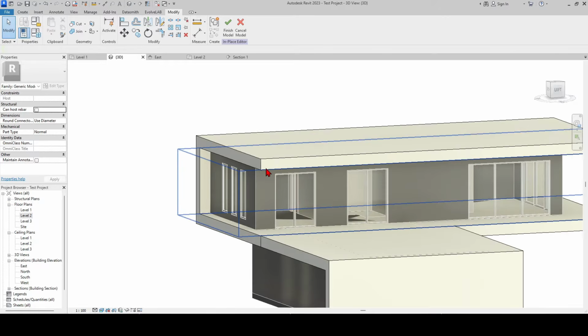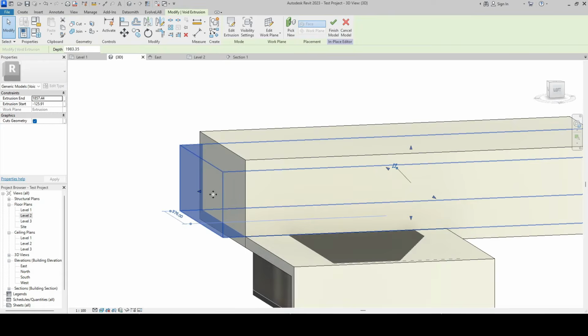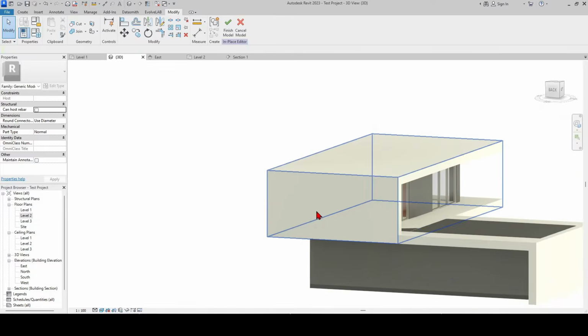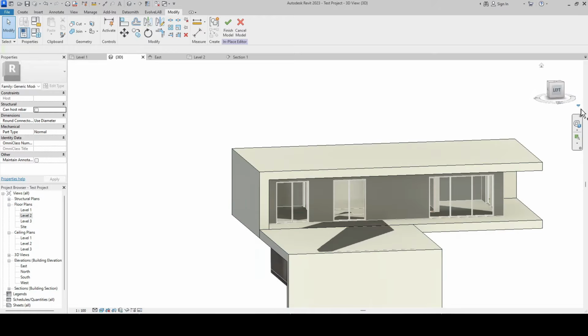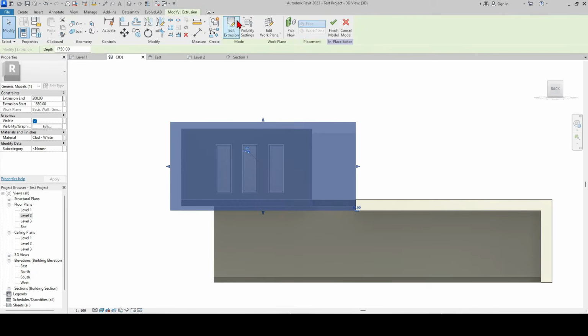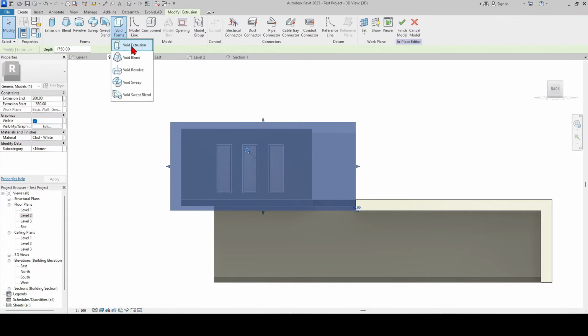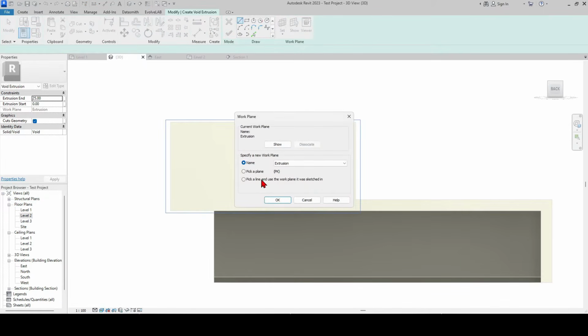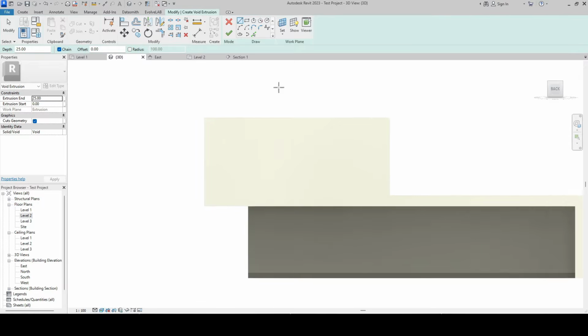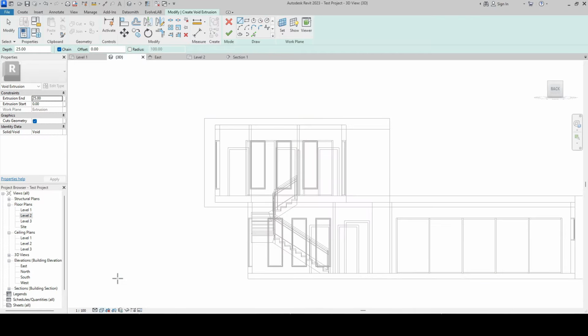Actually, I can merge the void part with the surface here. Of course, we will need to create openings for the windows later. Following the same steps, we should create void extrusion and set our surface. However, the windows in the back are not visible. Switch to wireframe mode so we can select the window frames.